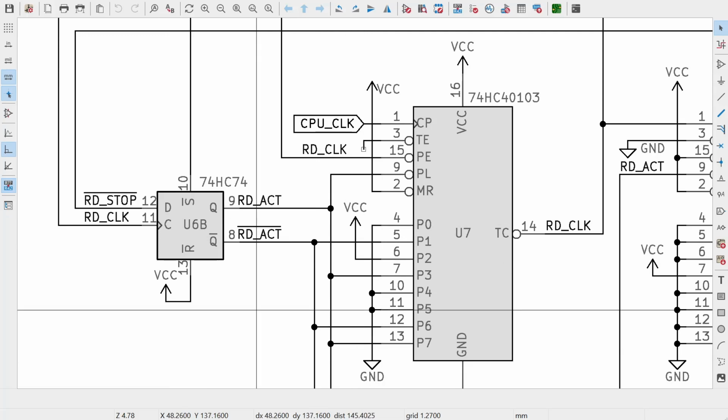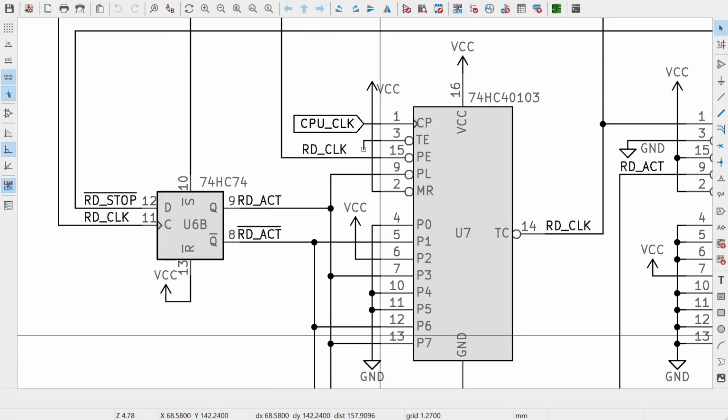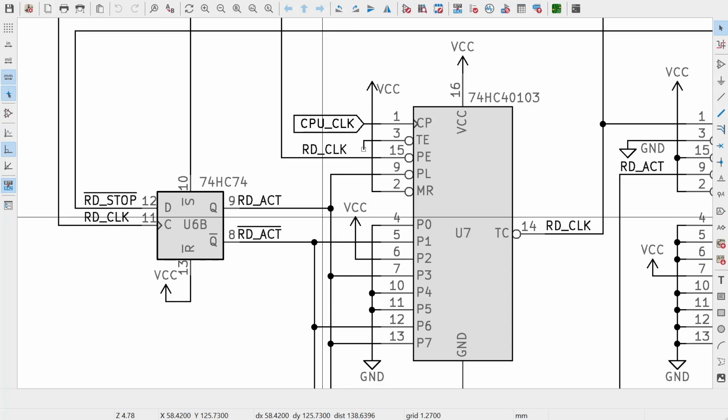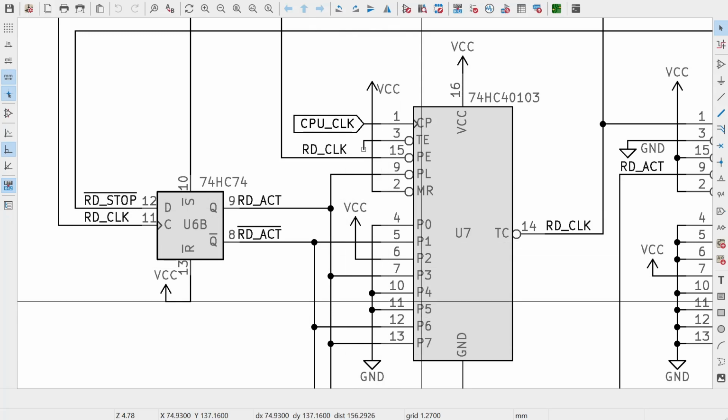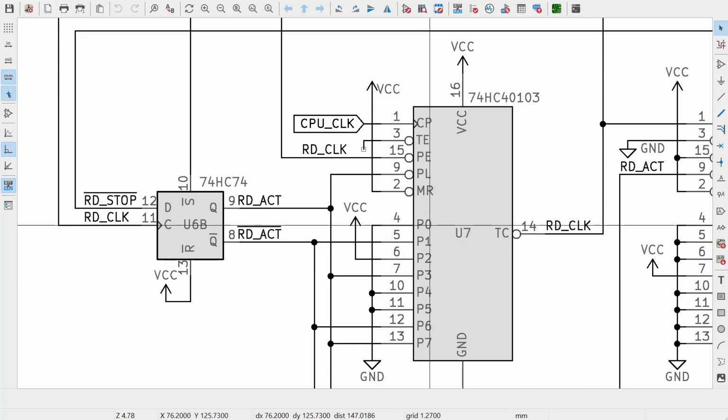I think the actual number I've programmed in here isn't correct, just looking at it, because it looks like when the flip-flop's off, we're going to get 0, 1, 0, 0, 0, 1, 0, 0, right? Oh no, we're going to get 0, 1, 0, 0, 0, 1, 1, 0, and that seems to be 70. So that's going to have a period of 71 because we have to include 0 as well, and 71 4 megahertz ticks is not the correct value for waiting from the start of the start bit to the middle of bit 0. I think I said earlier it should be 52 or so.